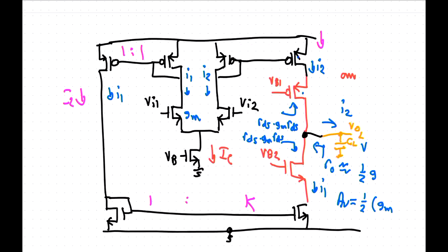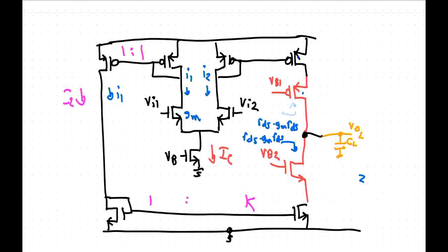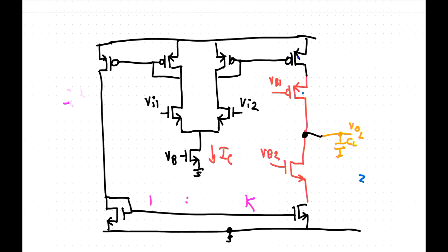Okay, so let's get rid of most of all of this. Okay, so if you think about how it is that we make high gain amplifiers, OTAs, whatever, then it's about taking a current and dumping it into a high impedance node. If that node impedance is high, we get a high gain. If we make it very high, we can get a very high gain.